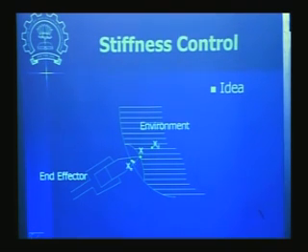Then what will happen? See, the robot is trying to reach this point xd, but once it reaches this xe point, it touches the environment. Now it cannot move further, but it will still keep on applying the torque corresponding to the error, which is xd minus xe multiplied by the proportional gain, to the motors. So it will keep on applying that much torque, which will correspond to, in some sense, applying the force. Do you see how this stiffness control works?